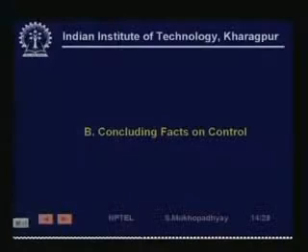Then you need to provide provision for manual bias. Manual inputs are very important, and you may like the operator to sometimes provide manual bias. That is, if the operators are very experienced, they themselves can sometimes act as very nonlinear and sophisticated controllers. So, if he does not like the PID output, you might like to give him an opportunity to change it. Having said this, these are typical implementation features, and now we will come to some facts on control.